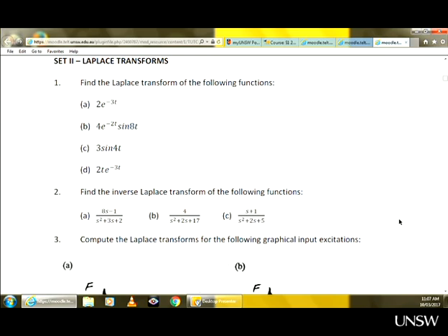When we want to find the transfer function, I thought that maybe we should use initial conditions. The transfer function assumes zero initial conditions. But if the output is based on non-zero initial conditions, then you can't use the transfer function. You have to go back to the differential equation and find the output. So the transfer function uses zero initial conditions.